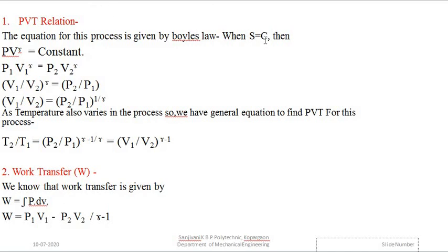So when S is equal to constant, then PV to the power gamma is equal to constant. This is the governing equation for us. We are applying this governing equation to the state points 1 and 2. So we can write P1 V1 to the power gamma is equal to P2 V2 to the power gamma.